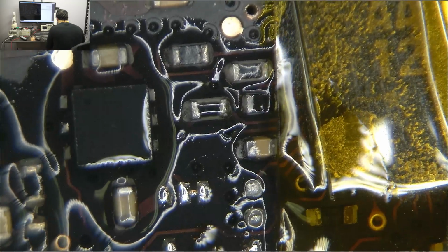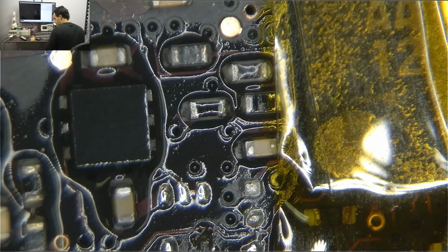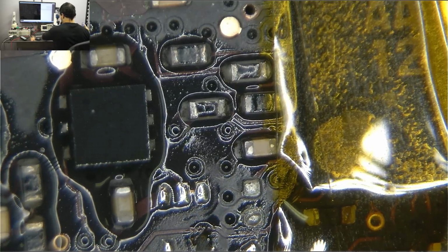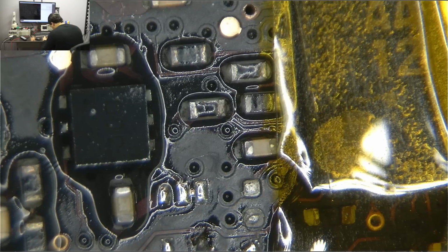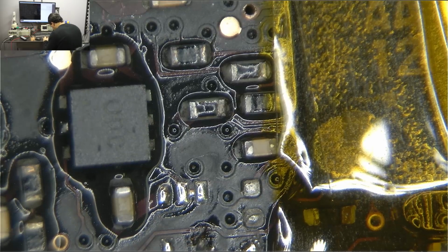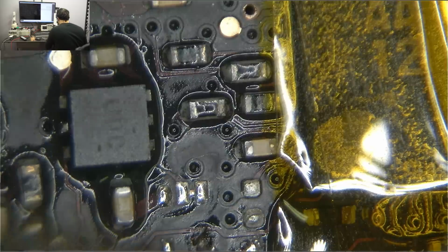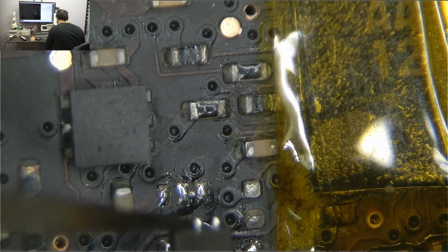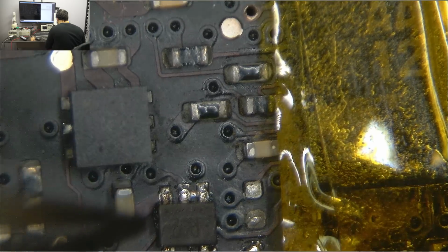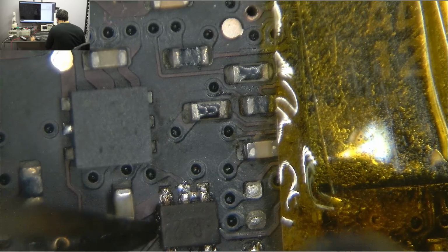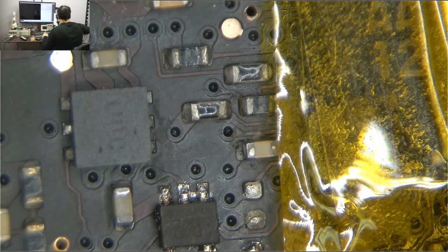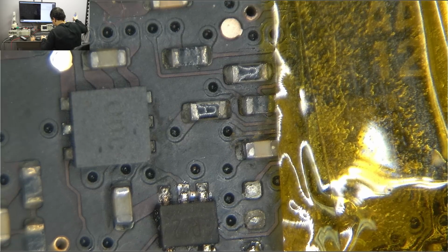So we're going to put that new component on there, and then we're going to go from there. I like to minimize misery in troubleshooting, so I want to try to get rid of as many problems as I can at once, and that's my goal. And since this thing really is less than 17 cents to me, I can't say I care. I'm also going to try my best to not reflow the SMC, which is right next door. There's really no need to reflow the SMC if it works. That's just a nightmarish thing to do, and there's just no reason for it.